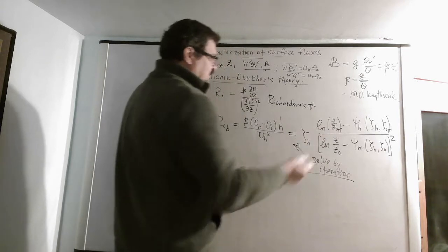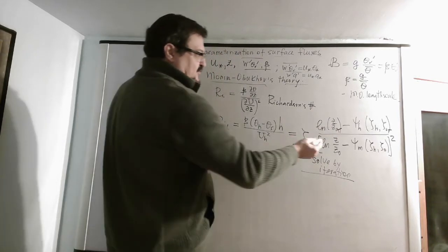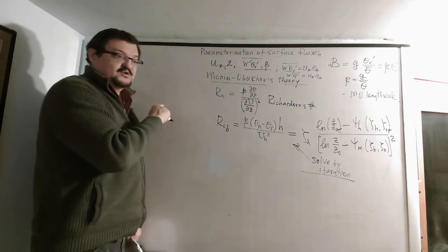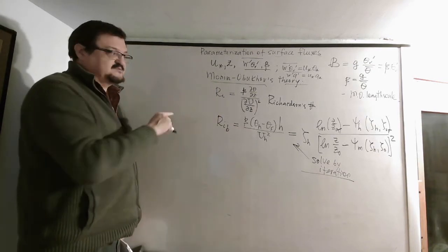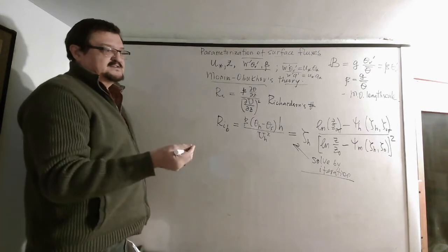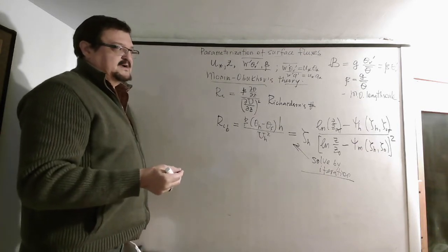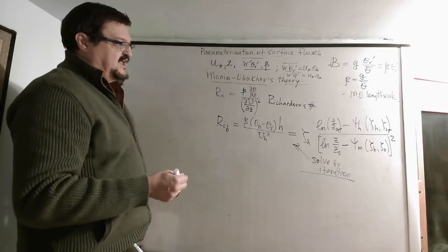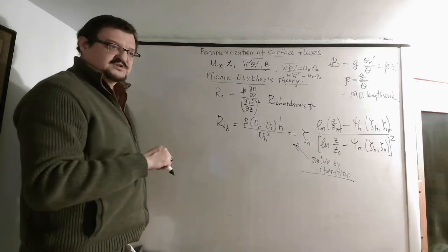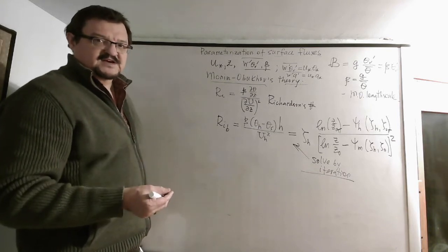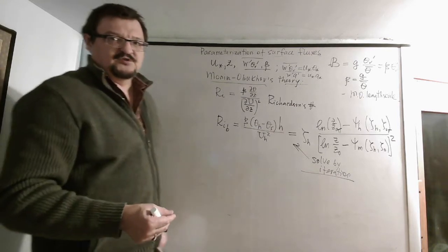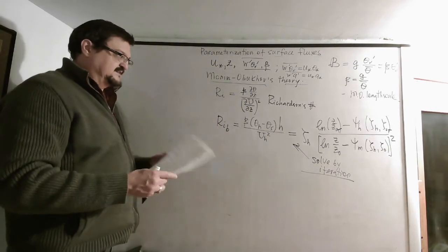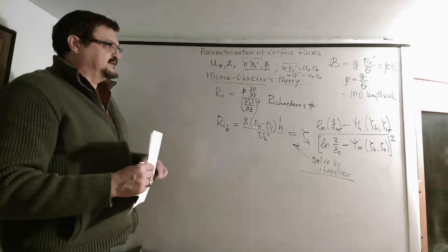But anyway, you can solve this, and as long as you find your eta, then you substitute it into your CD and CH expressions that I wrote before. You find your bulk hydrodynamic coefficients, and then you substitute them into the bulk formula. You compute your fluxes, and then you use those fluxes in your model as your lower boundary condition. So basically, that's all. Maybe a little comment.